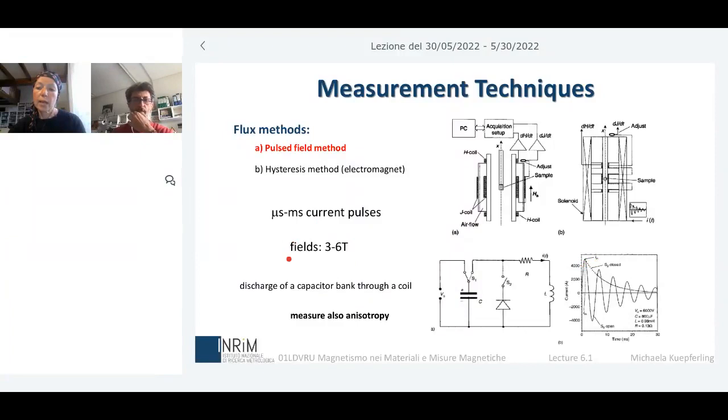And required, as I told you already several times, is, let's say, 3 times the coercivity of a hard magnetic material. For samarium cobalt, you would have to go up to 7 Tesla, for example. So then you need this 7,000 ampere, something like that, that you have to push through your copper coil.